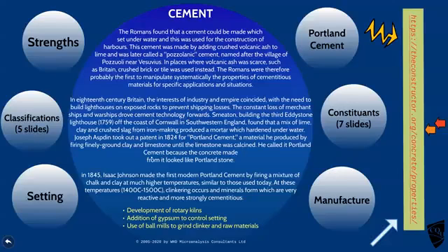And then things that came along to improve the situation were the development of the rotary kiln, which rotates and mixes it as it's heated, adding a bit of gypsum to control its setting speed and characteristics, and the use of ball mills, i.e. a rotating container with big steel balls in it, which crushed up the materials. And these could all be put in series to create a factory.